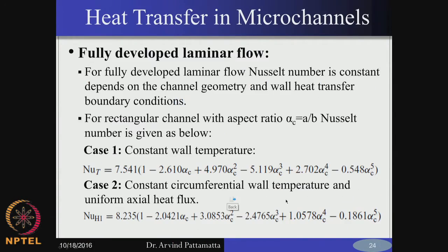Whereas if you go to the laminar case, we have constant values here. This does not tell you what the effect of roughness is. Kandlikar's model is only limited to the friction factor prediction, the use of constricted flow Reynolds number. When you go to heat transfer, we do not have a very satisfactory theory to account for the roughness on the Nusselt number.